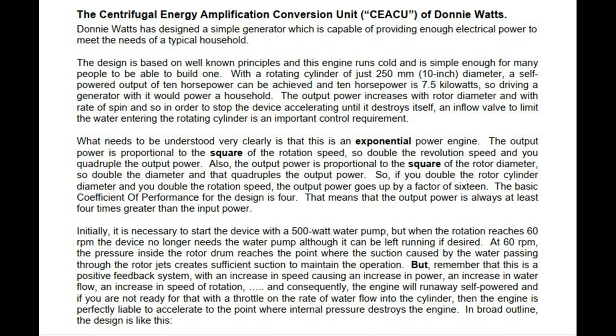At 60 RPM, the pressure inside the rotor drum reaches the point where the suction caused by the water passing through the rotor jets creates sufficient suction to maintain the operation. But remember that this is a positive feedback system, with an increase in speed causing an increase in power, an increase in water flow, an increase in speed of rotation.